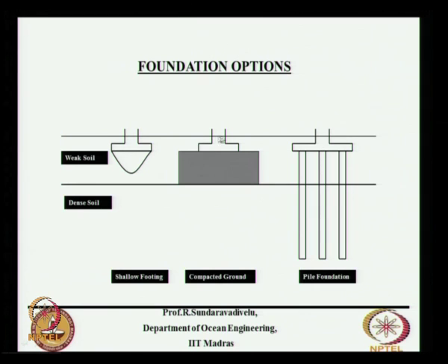Suppose you are putting a breakwater here, you cannot put a pile foundation for a breakwater, it will be very expensive. So in such a case it is better to improve the foundation, allow the extra stones to be filled, that also is a possibility. When you dump it, the soil will flow and the stones will go down, then allow for the settlement to take place.